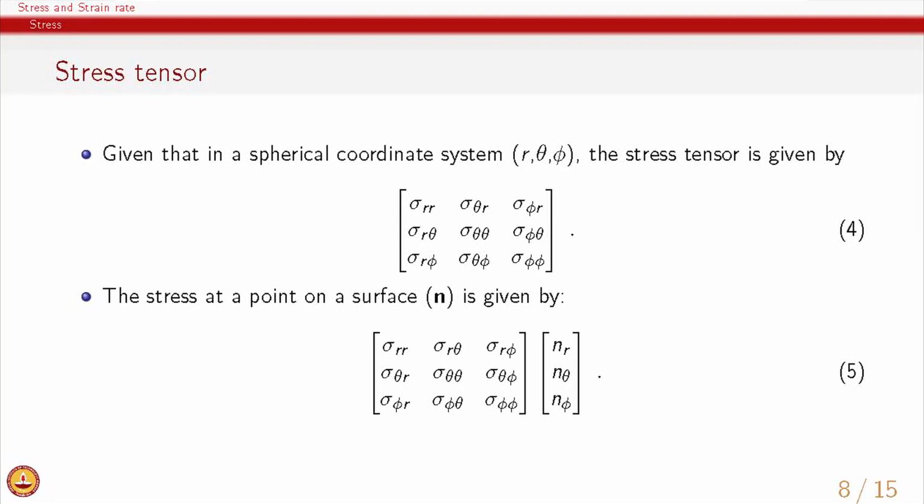So, in fact, we will see that the presence or absence of normal stresses, as we saw in the unusual flow phenomena lecture and where we also discussed rock climbing and other such effects which were related to the normal stresses. What we will see is in fluids we will try to impose sigma theta phi or sigma phi theta using a cone and plate geometry, and if we measure sigma rr and sigma theta theta, we will get a very good indication of the elasticity of the material, or what the basic viscoelastic behavior of the material is, if we subject the material to sigma theta phi and then measure the normal stresses which are generated.